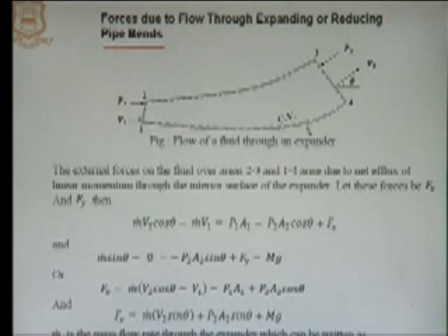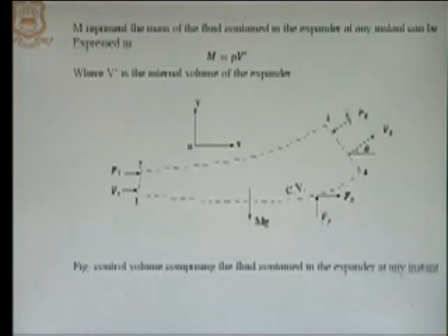develop the free body diagram of the fluid, and once we develop the free body diagram of this fluid which is enclosed between section 1, 2 and 3, 4, we can find out the force on this fluid, and once we can find out the force on this fluid, reaction of those forces will be the forces on the bend itself, right. So, we have developed this free body diagram.